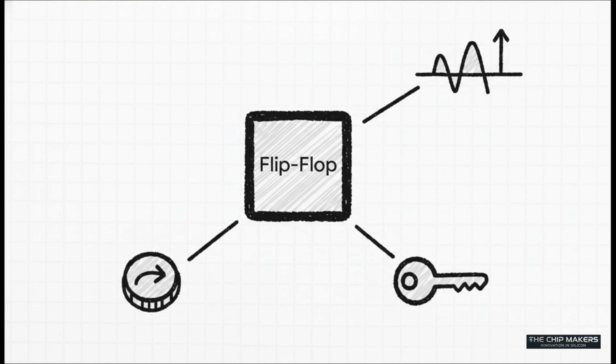And man, the library gives you a dizzying variety of these memory bricks. I mean, it's wild. A designer can pick one that grabs data exactly when the chip's clock signal rises, or one that acts when it falls. They can get a flip-flop with a reset button and even choose if that reset should happen instantly or wait for the next clock tick. The library has dozens of these pre-built combinations, which lets the automated tools pick the absolute most perfect, most efficient one for every single bit of memory on the entire chip.